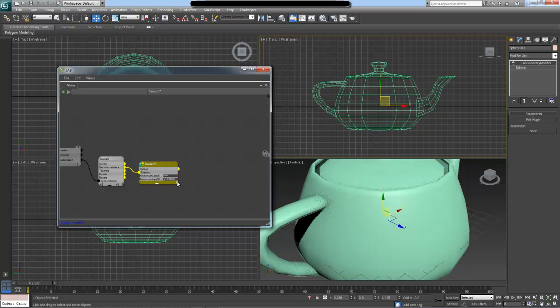It takes some parameters which are currently not initialized, but I will just set the default values to 5 for my minimum leaf size. This is the minimum volume of the volume hierarchy it uses to optimize its algorithm, and I will use 5 for the minimum leaf element. These parameters are not really important as long as you keep them kind of on the low side, but this leaf size parameter really depends on the scale of the scene you're using. 5 is a decent acceptable value in my scenario.